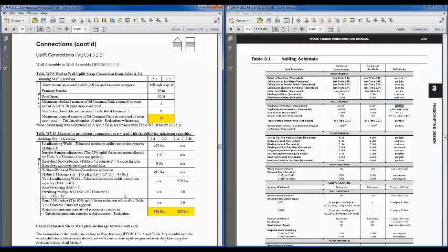In the wood frame construction manual, we cover both the perforated shear wall and the segmented shear wall approach. We do not cover force transfer around openings. Force transfer around openings is covered in the wind and seismic standard, and so there are these two approaches, perforated shear walls and segmented shear walls, in the wood frame construction manual.